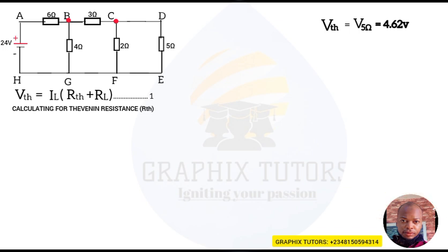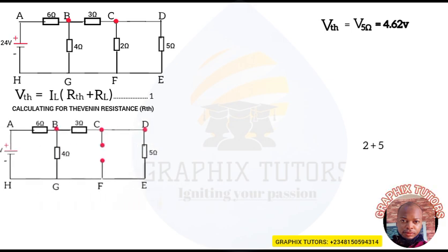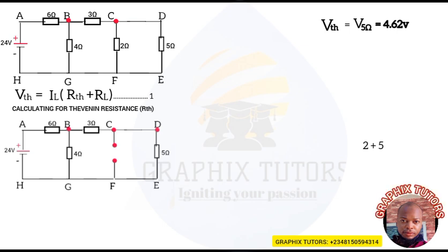So when you're looking for Thevenin resistance, you are going to go back to the parent circuit. You remove the 2 ohm resistor. You now short circuit the 24 volt voltage source there, because that is the voltage source. If it was a current source, you would open circuit. Are we there? So this is what you'll be having. So here's my RTH, this opening you have here because you've removed the 2 ohm resistor.